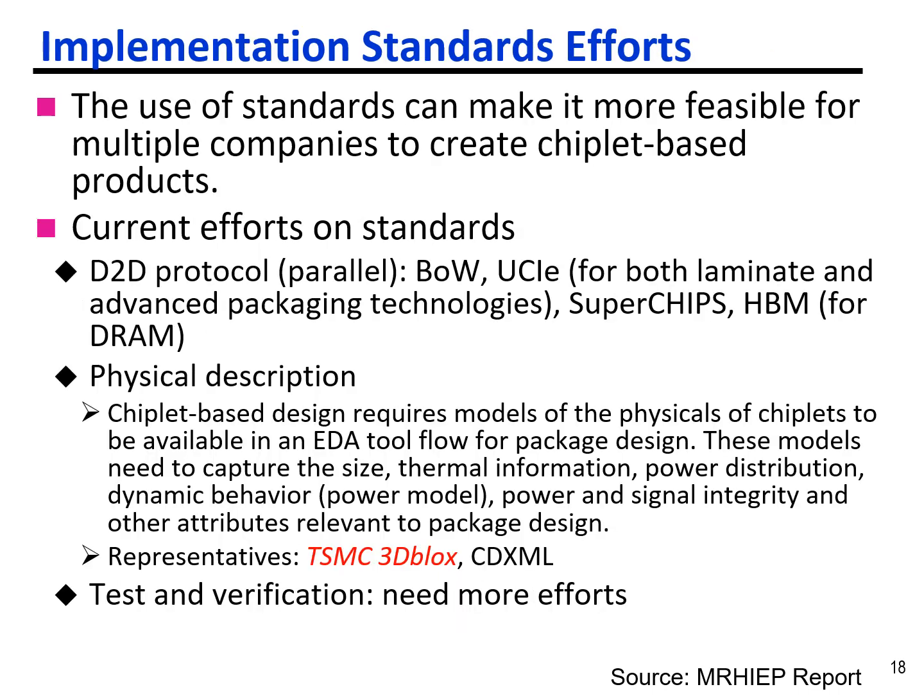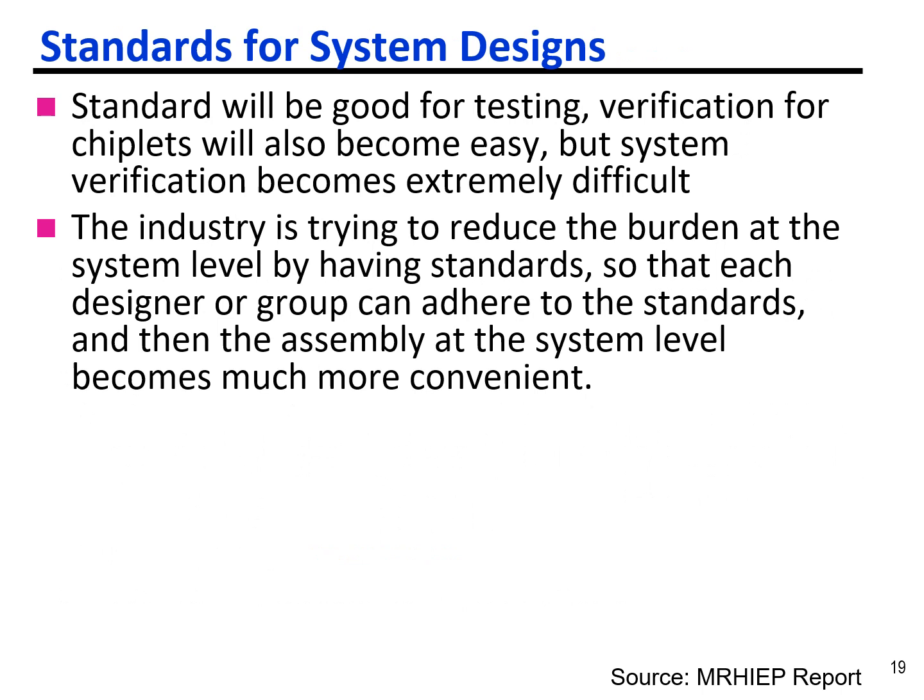And currently we have some standards, including the D2D protocol, the BoW, UCIe, super chips, and the well-known HBM. So in physical description, we have another talk from TSMC to talk about 3D blocks. Okay, basically, I think this is a very good idea to try to have the chiplet-based design and also the building block methodology. Okay, so basically the standards for the system design will be good for testing, but the verification for the system will be very hard.